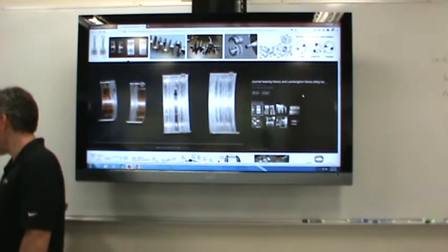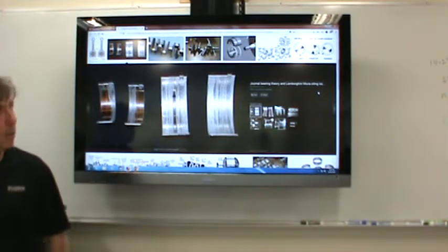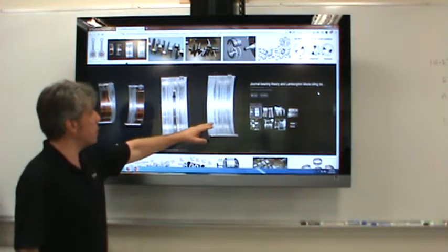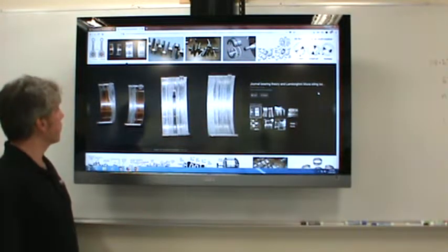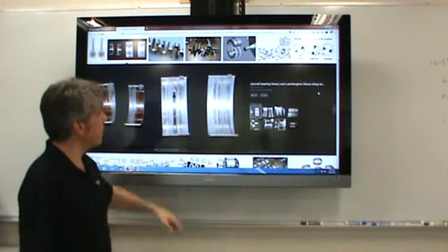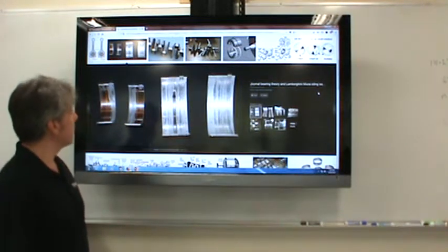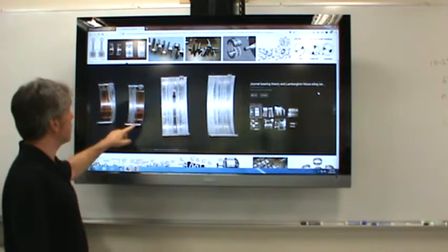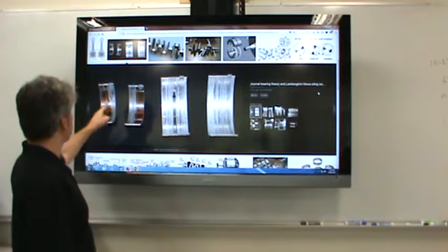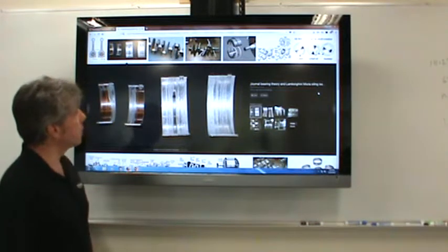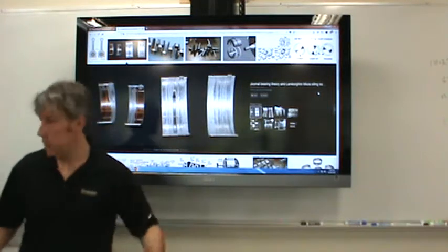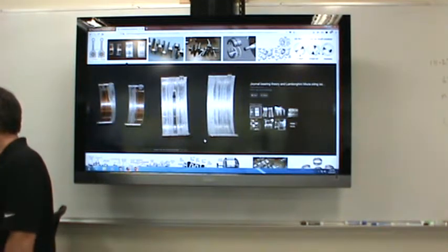Here's what happens when you don't have oil in the bearings like you need, and rubbing actually occurs between the crankshaft and the bearings. These look like rod bearings, and these look like main bearings. That's what I'm guessing they are. It's hard to say. This is a little confusing because usually you have an oil hole. These don't have that, so I'm not sure, unless that's what these grooves are for. General bearing theory and Lamborghini. I don't know what those are off of.